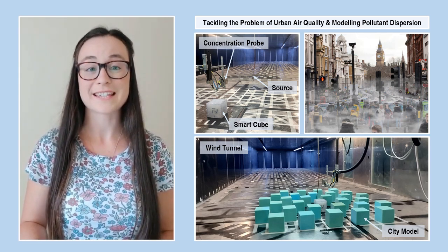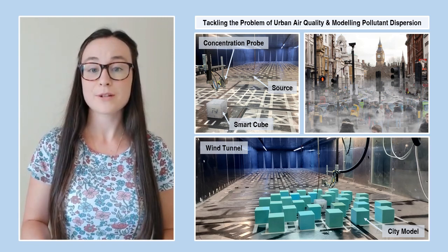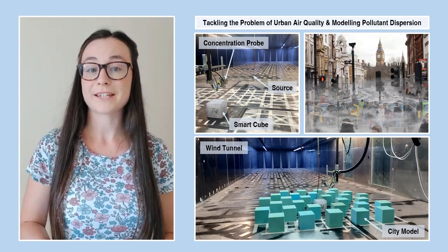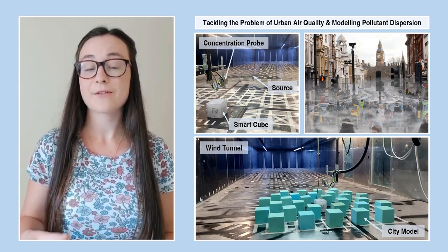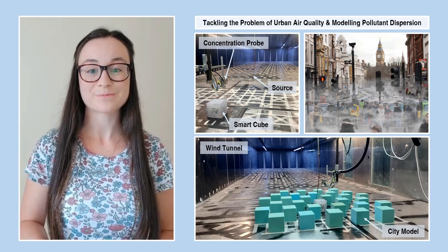My hypothesis is that pressure can be used as a proxy for concentration. Measuring pressure is much cheaper, simpler, and can be measured in multiple locations simultaneously. This would therefore simplify future experimental wind tunnel studies in pollutant dispersion.